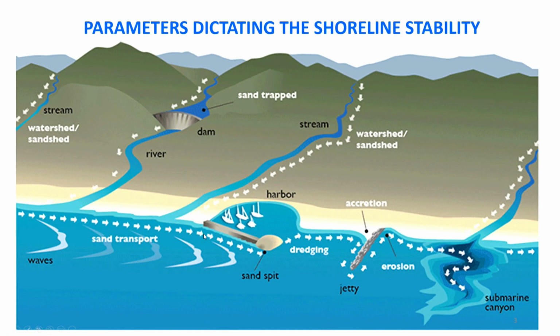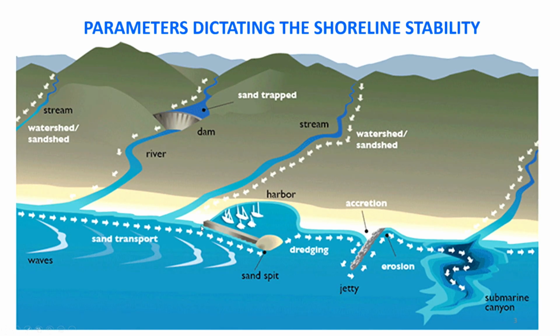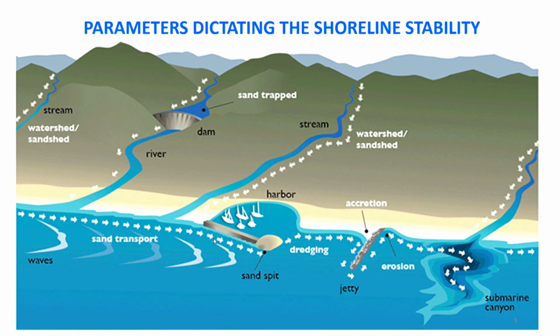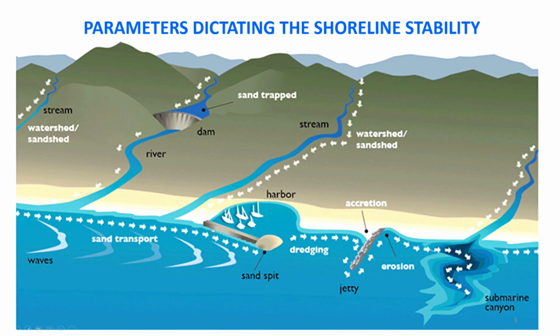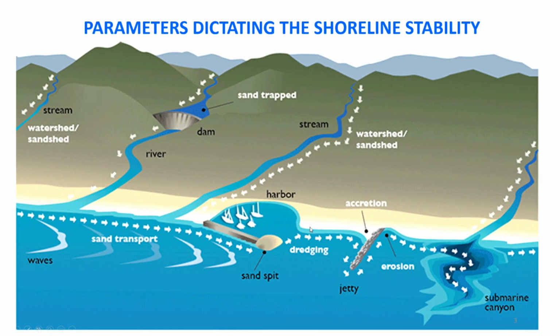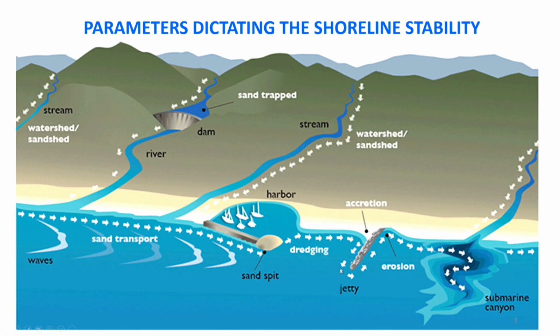Anyway, when this sand is constantly moving along the coast, and the moment you construct a harbor with some kind of structure which is termed a breakwater, then what happens? The sand gets deposited here slowly, and you see that a beach will be advancing towards the ocean. Whereas on the other side of the breakwater, the sand will be removed and transported. This happens in the case of any kind of obstruction.